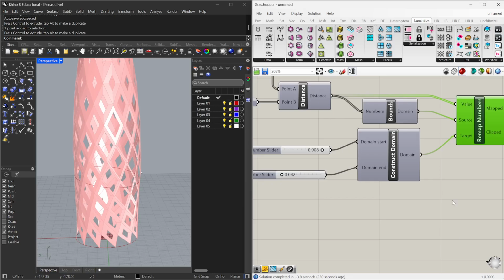I've gone through with you the Grasshopper interface. We've done a quick sketch of how we can create a parametric tower using some of these Grasshopper parameters. I've quickly gone through with you how to then put an attractor in there by saying, okay, according to certain numbers, a certain point in space, this is how big I want them to be. Can you see where else you might be able to apply that or use it within your own design work? What data could you use to dictate the size of these openings?